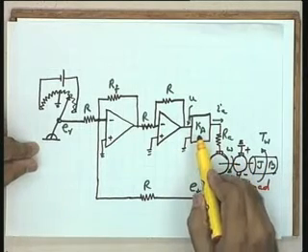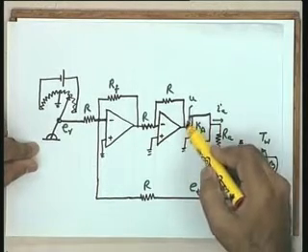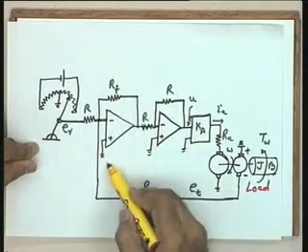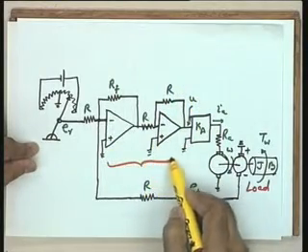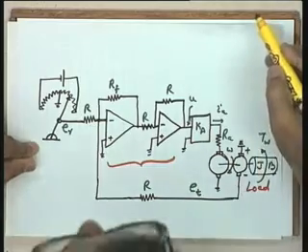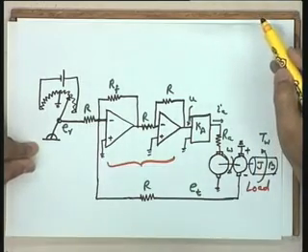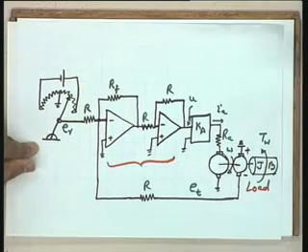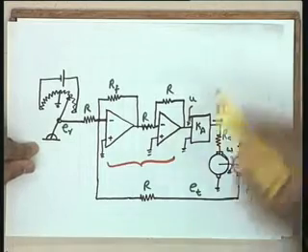Now, this actuator is getting the control signal U from a suitable controller. Here is the controller circuit, which in this case is a simple amplifier. At a later stage we will see that this controller could consist of complex functions like the derivative of an error signal, the integral of an error signal, or in general any function you could take at this point.